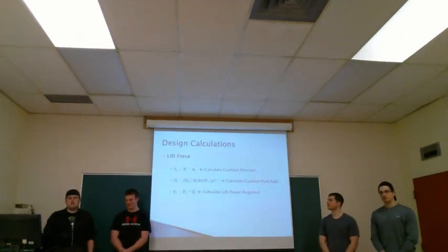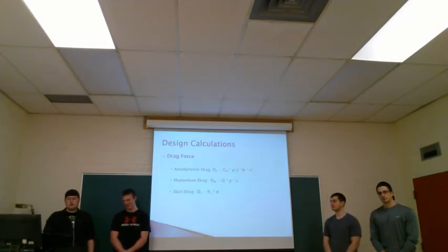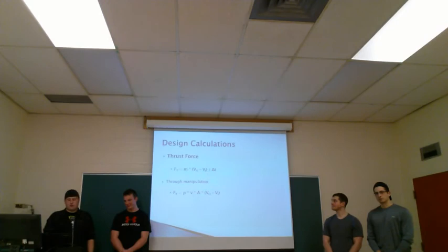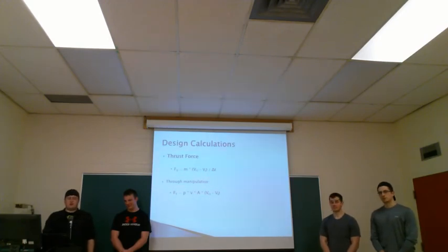For our design calculations, we calculated our lift force. We had to calculate the cushion pressure, the cushion flow rate, and the lift power that is required from our lift motor. For our drag force, we had our aerodynamic drag, our momentum drag, and our skirt drag. For the thrust force, we had to manipulate the thrust force equation to get the density, speed, and the area.